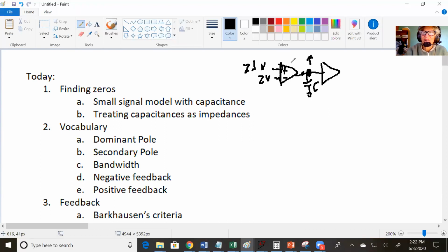So this right here is trying to set the voltage on that node. That means it's charging this capacitance or discharging this capacitance to change the voltage there. And the paths that put current on this node are not infinite current, so they are acting like resistors. So you have the capacitance contributed by the transistors, and because you don't have infinite current, that's behaving like a resistor, and you end up with something that looks like this.